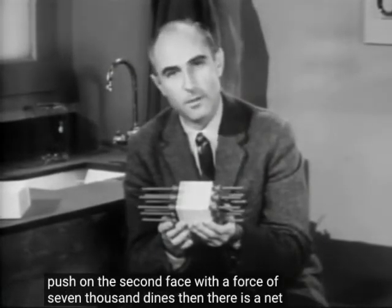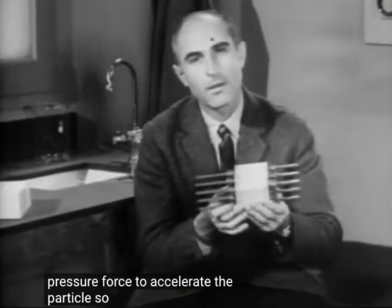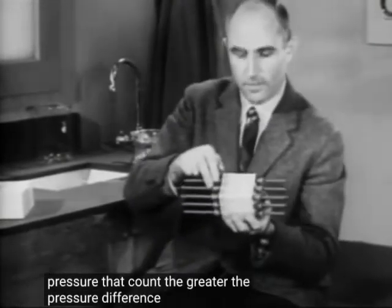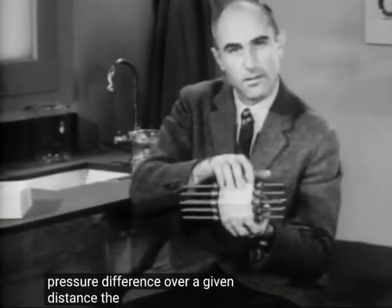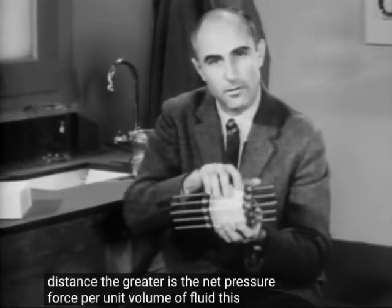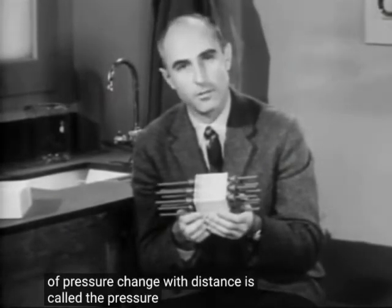Then there is a net pressure force to accelerate the particle. So it is differences in pressure that count. The greater the pressure difference over a given distance, the greater is the net pressure force per unit volume of fluid. This rate of pressure change with distance is called the pressure gradient.